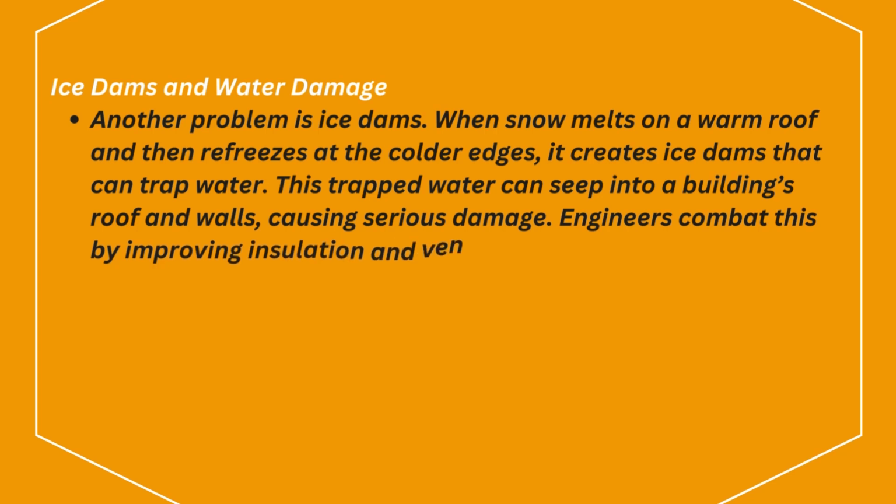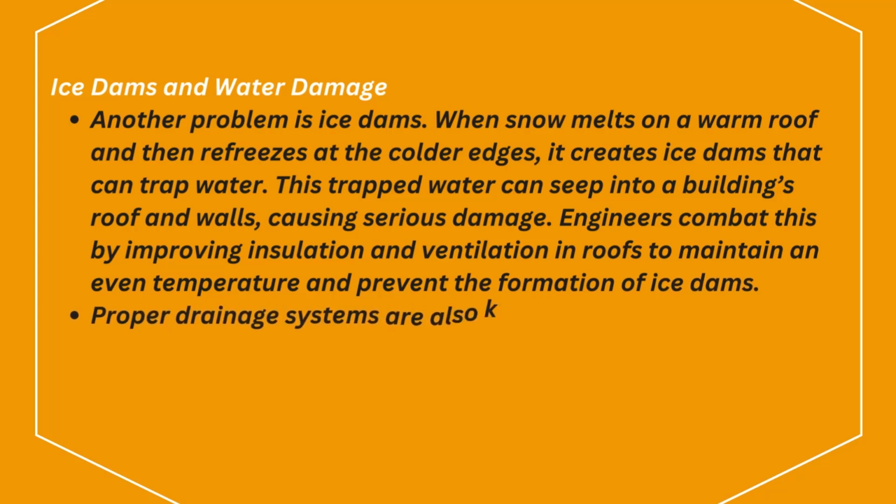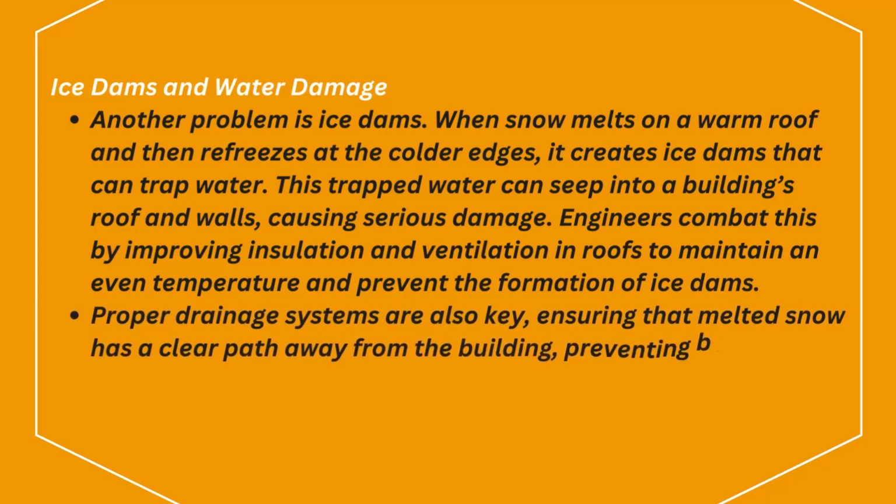Engineers combat this by improving insulation and ventilation in roofs to maintain an even temperature and prevent the formation of ice dams. Proper drainage systems are also key, ensuring that melted snow has a clear path away from the building, preventing both ice buildup and water infiltration.